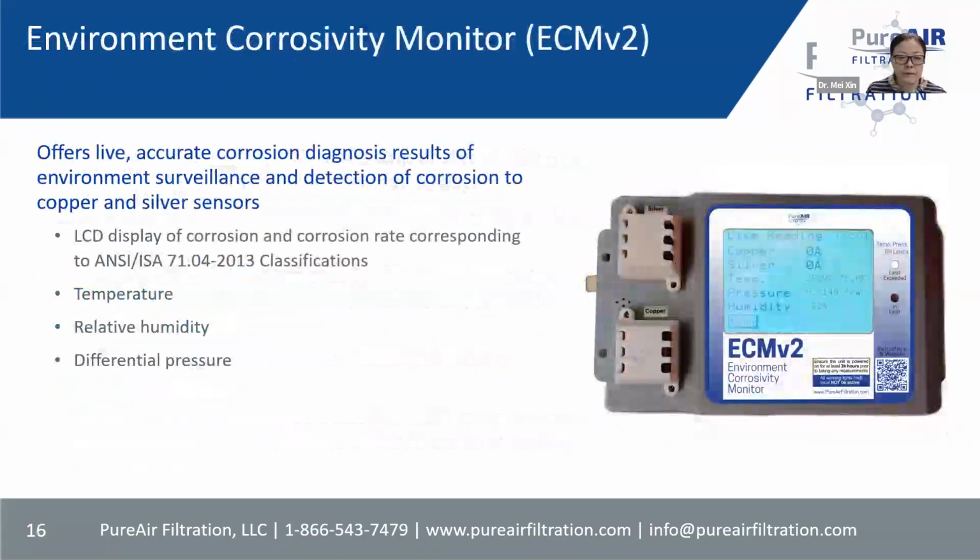Next is the Environmental Corrosivity Monitor, ECM version 2. This is an online, real-time corrosion diagnosis showing results at your site. You can put this in your concerned area and continuously monitor the corrosion ratings. It has copper and silver sensors built in for detecting corrosion, and the LCD displays corrosion and corrosion rate corresponding to the ISA standard.